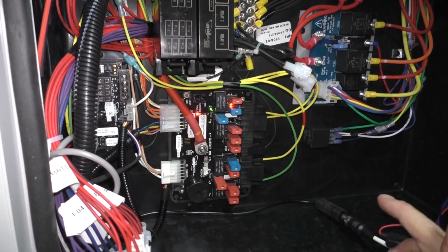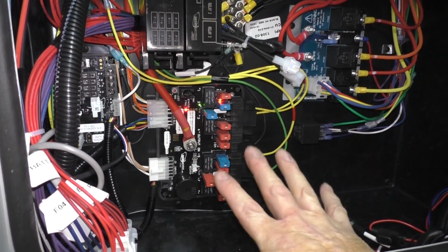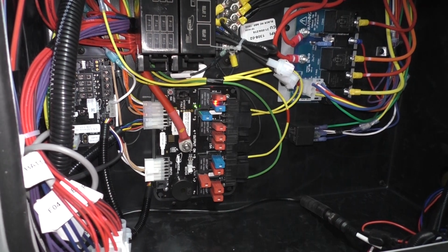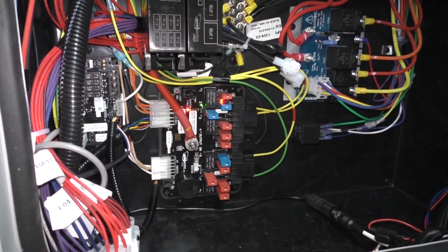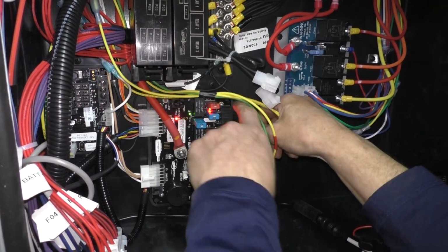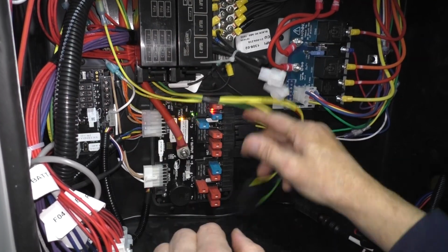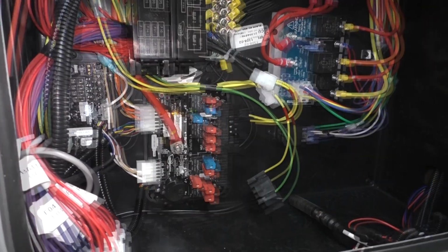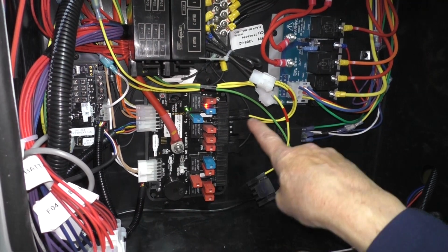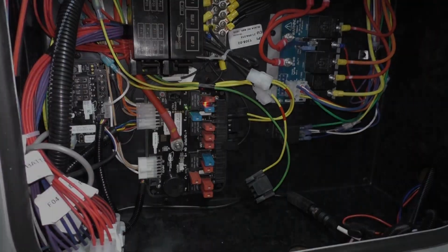When we go to page 6, the module will bypass the program that's loaded into it, so whatever's wired into switch 1 will be directly connected to relay 1. We can easily troubleshoot the switches, the switch harness, the switch backer board, and the LIN. But we want to unplug the outputs so that we're not turning anything on. This will save a lot of time. Just turn your switches on and watch the lights come on. You'll know if everything is working correctly. So if there is a problem, it may be in the wiring after it leaves the module.